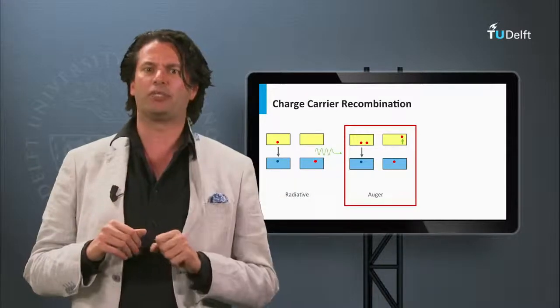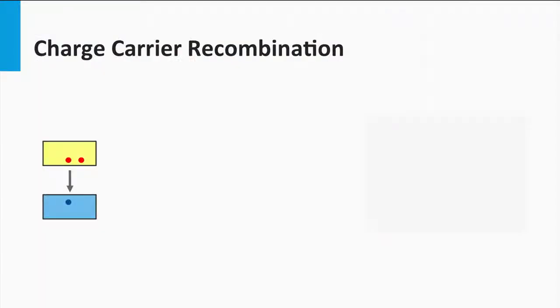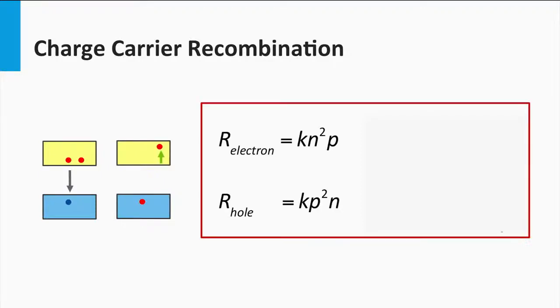Let's consider Auger recombination. Auger recombination is the process in which the momentum and energy of two recombining hole and electron is conserved by transferring energy and momentum to another hole or electron. This electron is excited in higher levels in the electronic band. This excited electron relaxes again such that the energy is lost as phonon modes. Phonon modes are lattice vibrations and is nothing different than heat.